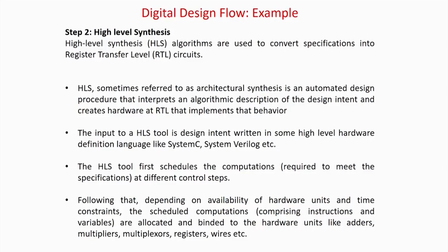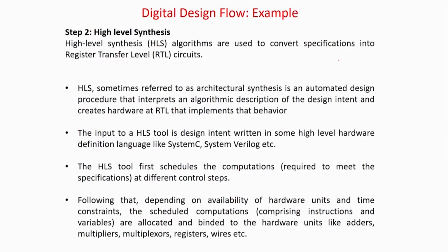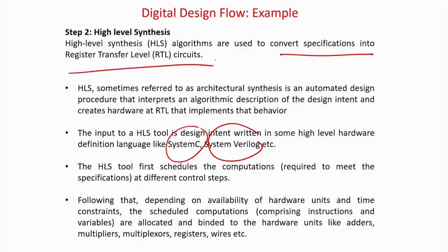In high level synthesis, such implementations, like the block diagrams, have to be written in an abstract language, like SystemVerilog or C, some higher level languages. The tools then convert these block diagram specifications into register transfer level circuits. Register transfer level means you have some registers, some combinational circuits, some registers, and so on. Then the combinational circuits will be synthesized at gate level by automatic tools.